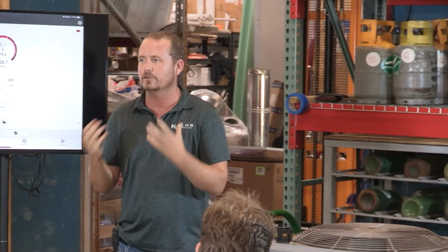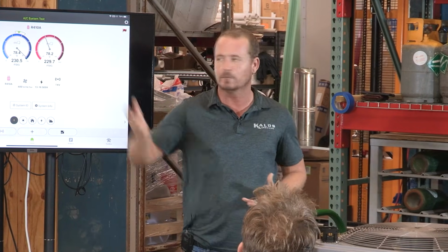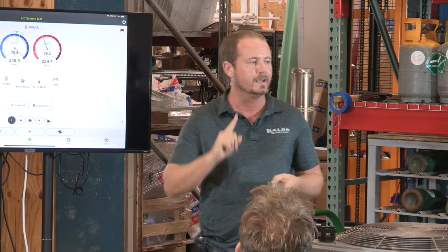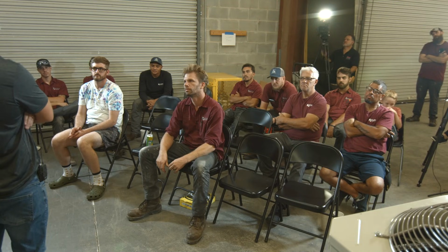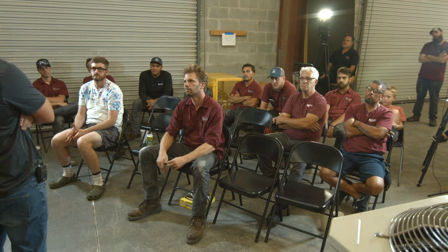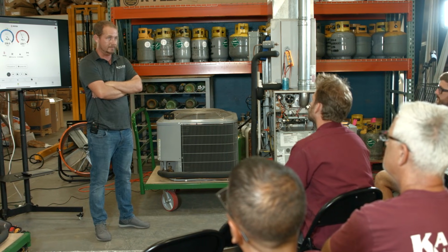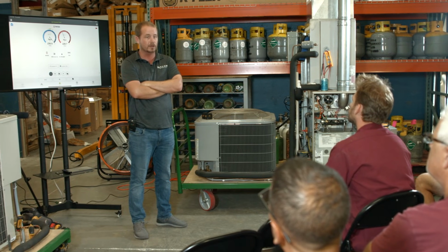And even after you do all that, once you confirm that, even once you look at the pin settings, even once you test to make sure you have a 24-volt call on G and Y/Y2, did you check airflow? The answer is no. I'm not saying that you did anything wrong, because you didn't, but don't say you checked airflow, because you didn't. What would you have to do to check airflow?